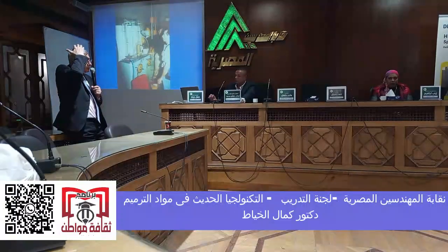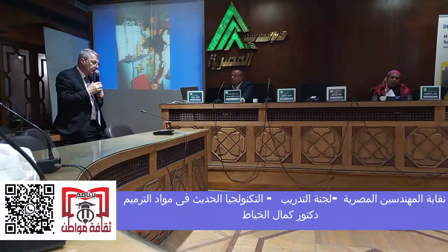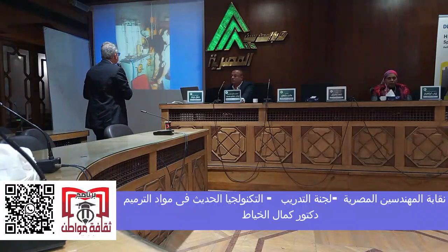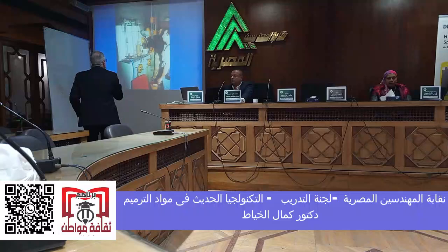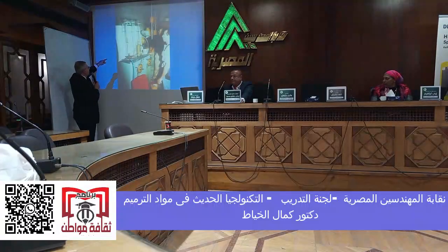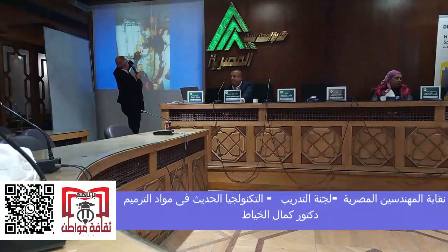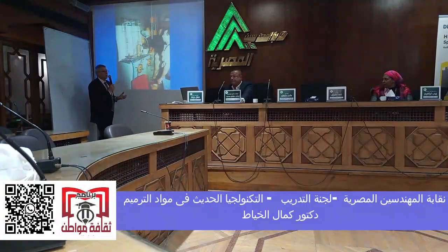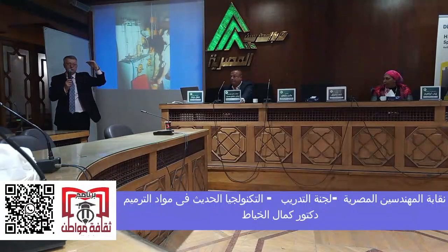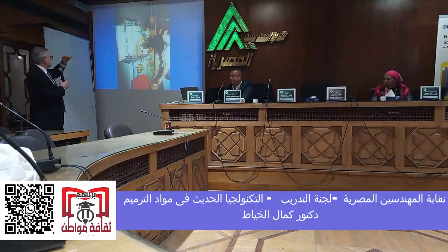You also want your grout to be able to penetrate very small cracks. One test we found is from the French standards, called the sand penetration column. You have a graduated column of white sand, and you put grout in it and, under pressure, you grout it, and you see the depth of penetration in this sand column. The sand column is probably 30 centimeters in height.